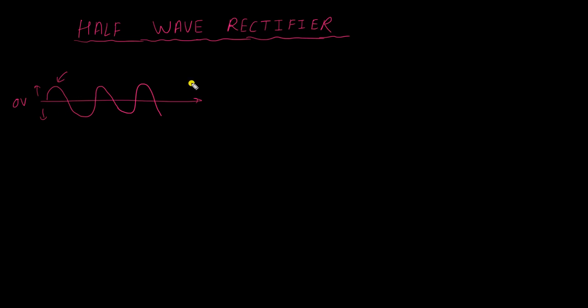So if we want to convert to DC, DC means direct current, or we can say a direct signal which has only one polarity. Getting one polarity means we have to get only the upside, or we can also say only the downside. Since we want only one polarity, that is known as DC, but AC has dual polarity. As much as there is above, in the same way there is also below. So the total area in the above cycle and the below cycle are both the same.